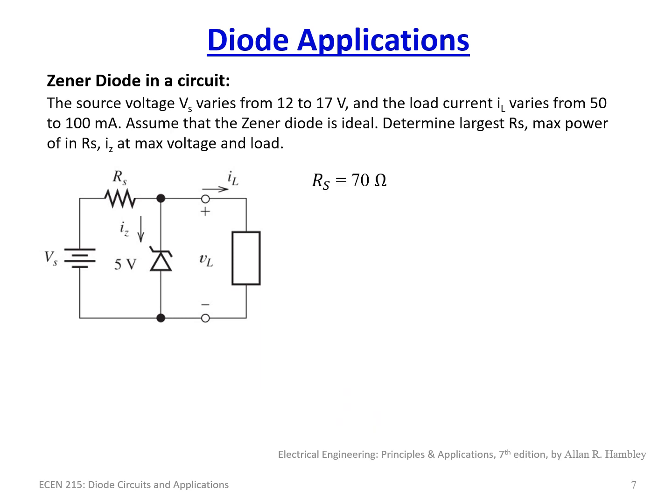Now, given this, we can now solve for everything else. For power max, we can use V squared over R, which is looking at the drop. And for Rs here, we have Vs minus Vd, so we have whatever our possibilities for Vs is. So we have 12 volts up to 17 volts. And so Vd is fixed at 5 volts. So we have this range. And of course, R is now set to 70 ohms.